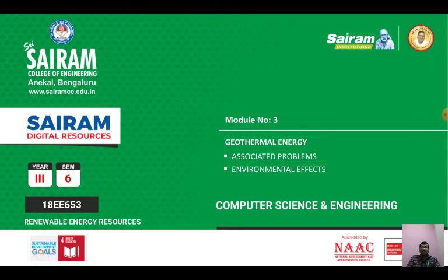So, we have seen the binary cycle power plant, where heat from the geothermal water is used as a vapor, which is used to vaporize the working fluid in separate adjacent pipes. The vapor powers the turbine generator. So, a heat exchanger is where the heat is transferred from geothermal water into the second liquid. So geothermal water is never exposed to the air.